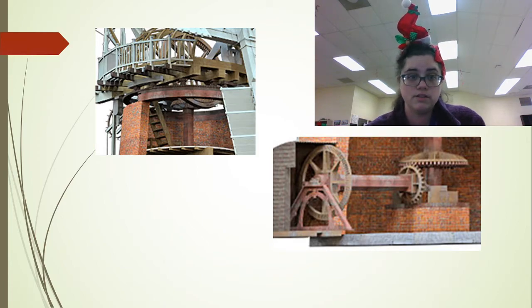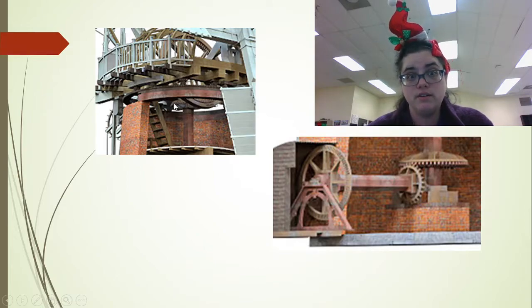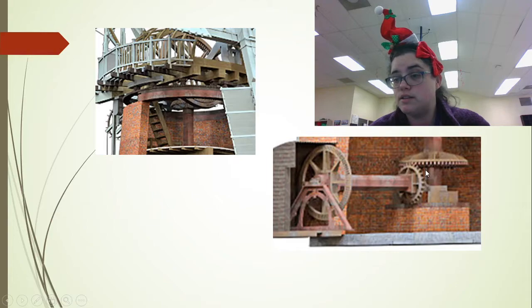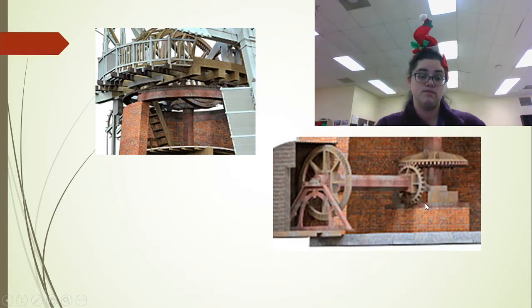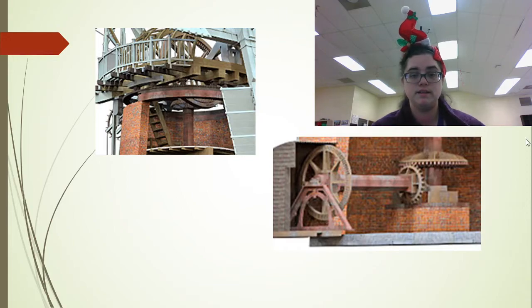And there's a closer up picture. There's some sort of assembly at the top that changes it to vertical. You can see there's an internal gear right there that's beveled. And this guy here is the vertical. It rotates along the horizontal axis. This one rotates around the vertical. And then it pushes it down to the bottom. And there's the mechanism there. Actually, these are at a bevel. These guys are at a bevel. The cogwheels in the video y'all watched with the Dutch guy living in the windmill, that one had some of those cog and crown and pinion things.